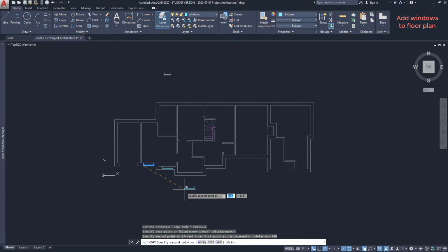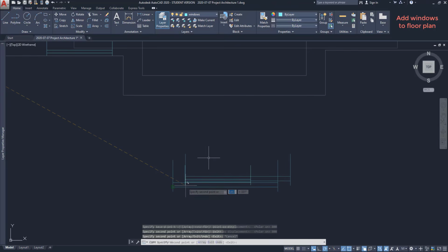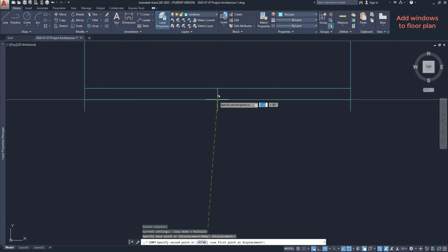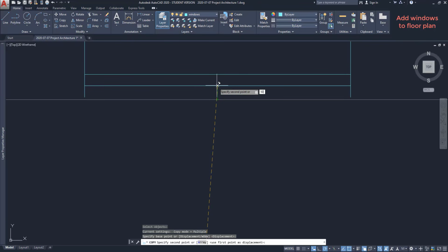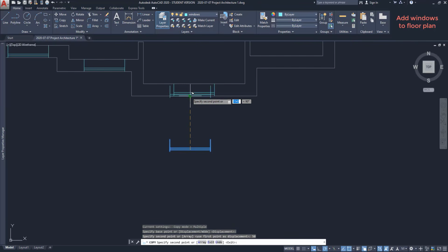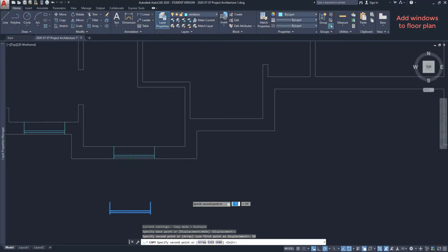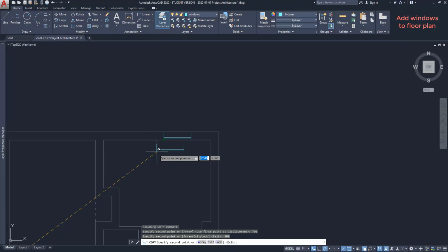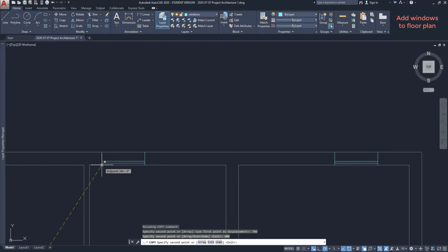Important. It's always good to have a window beside the drawing, so I can copy it when necessary. To place a window in the middle of the room, I choose a base point in the middle. Then I click on this midpoint, move it up and type an extension of 50 to place the window exactly on the correct location. Then you just need to continue putting all the remaining windows on the drawing. Just follow the PDF file.